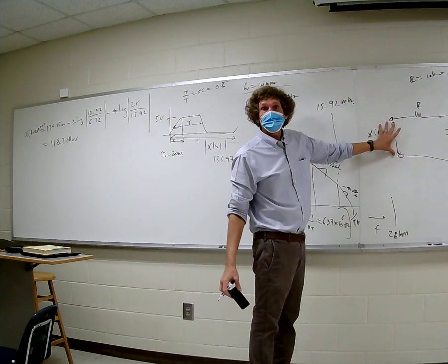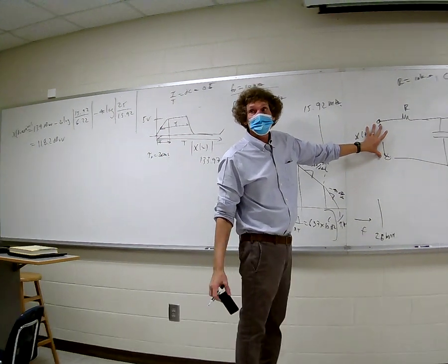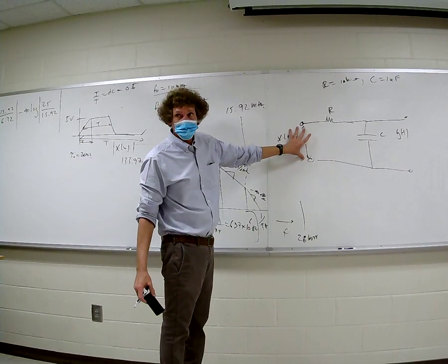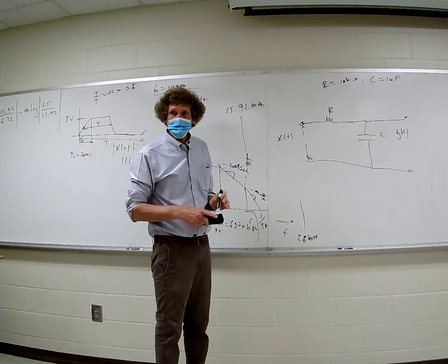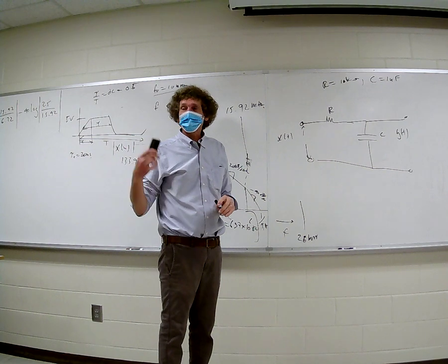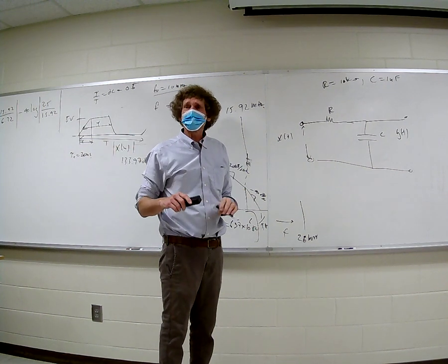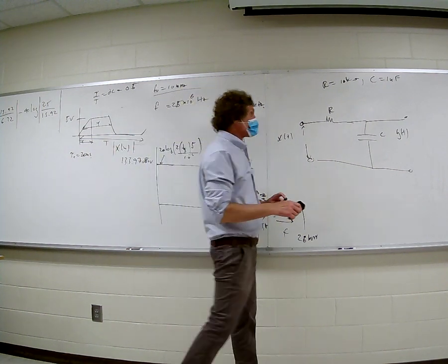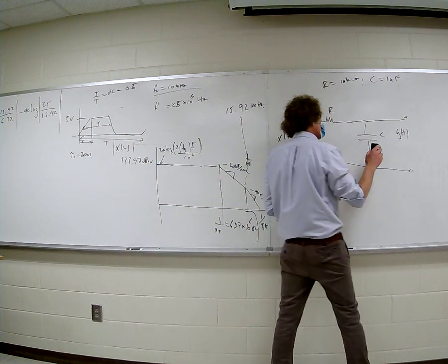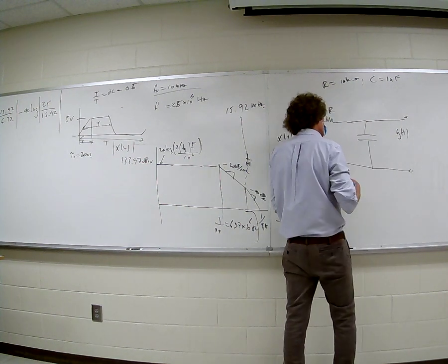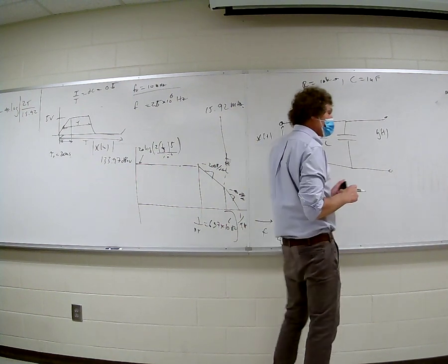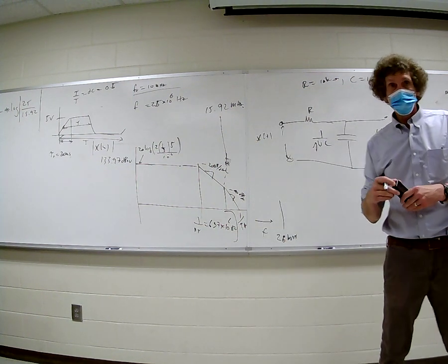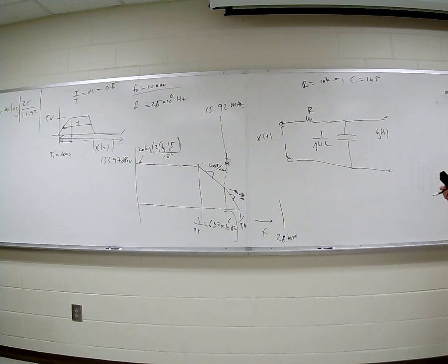Now we're going to find out the effects of the filters. So the first thing you do is find H of omega. Or H of S, but H of omega, probably I better say that. It's really going to be H of j omega now, but just leave it as omega. You don't need to worry about it. So when I do this, what is the impedance of the capacitor? It's 1 over j omega C, correct, class? You agree? Impedance is 1 over j omega C.